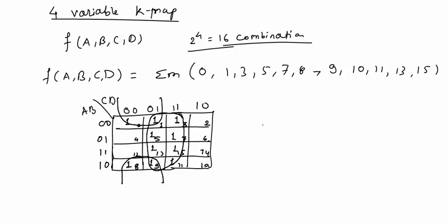And for this the expression will be written as f equal to, sorry, we have one more one here, and to cover this one we will have these 4 ones adjacent to each other. So there will be 3 combinations, 2 quads and 1 octet, and the expression will be written as f equal to a b bar plus b bar c bar.